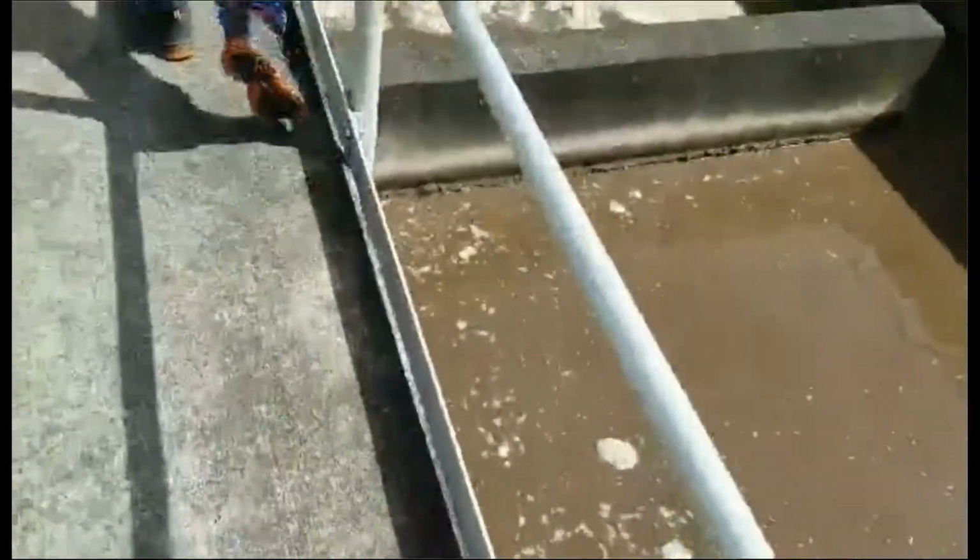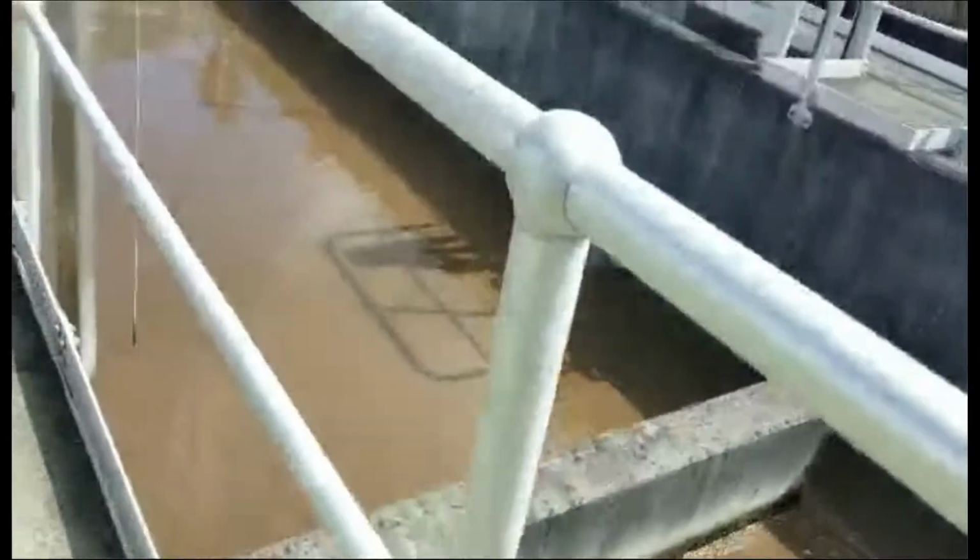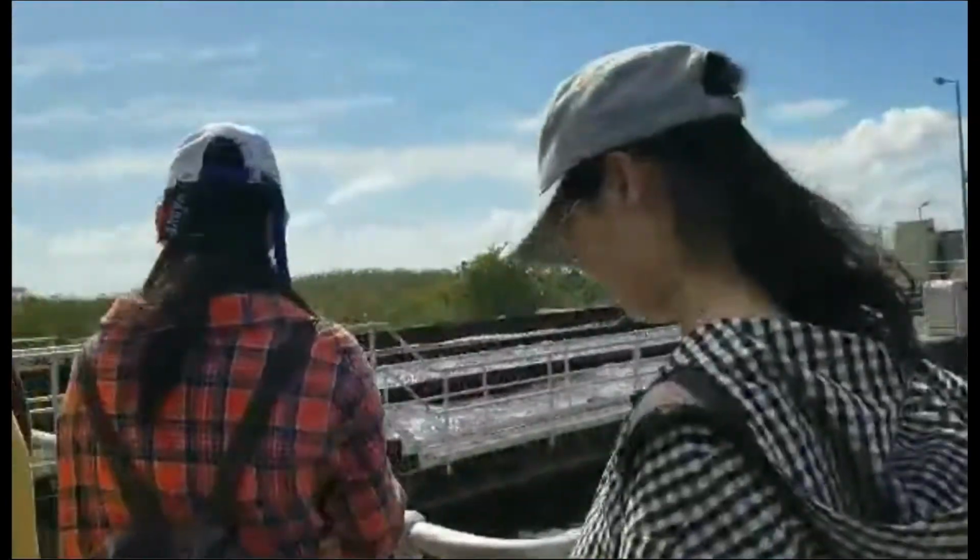Microbes get the required oxygen supply by blast aeration. The biofilm grows thicker, and microbes inside undergo anaerobic metabolism from lack of oxygen. Together with aeration, this causes the old biofilm to shed and promotes the growth of new biofilm. The flow of the biofilm will vary depending on the water outflow.